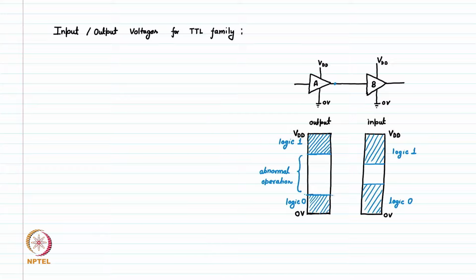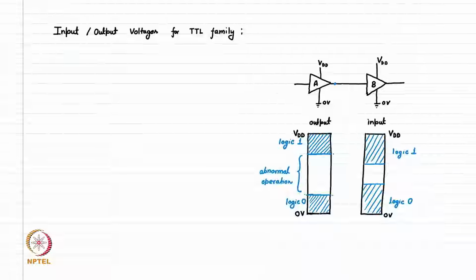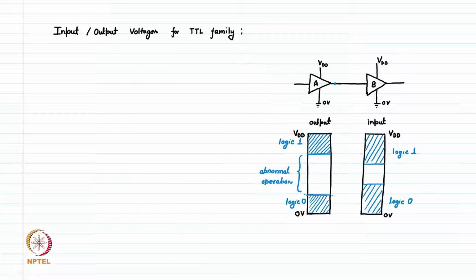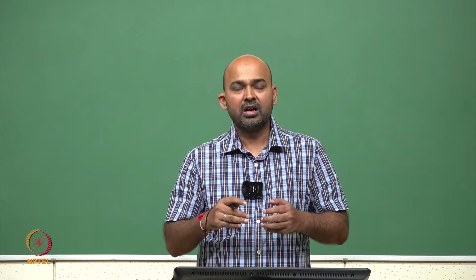Here we can have one question, why not we put these values equal. For example, this is the point where I detect output as high. This should be the same as at the input of logic B. The answer is, many a times these logic gates are not perfect.